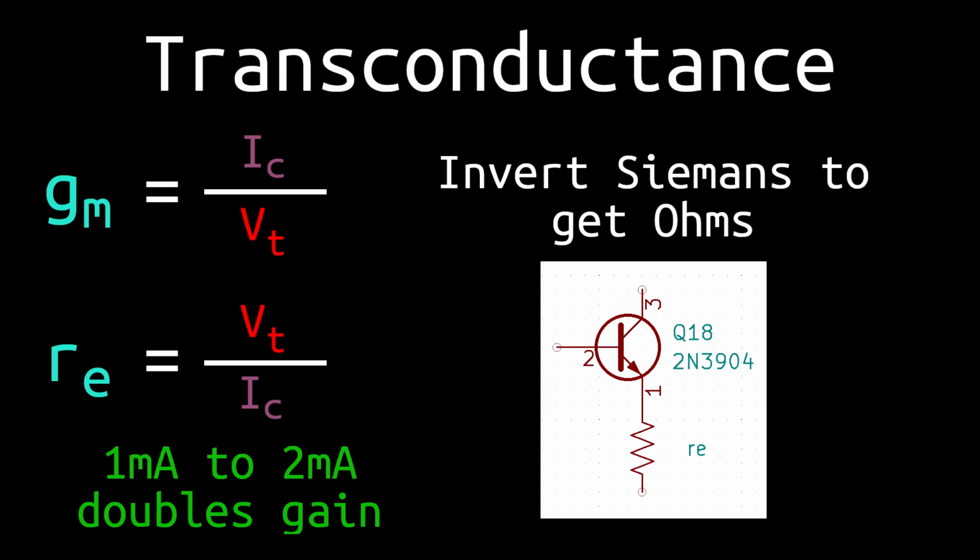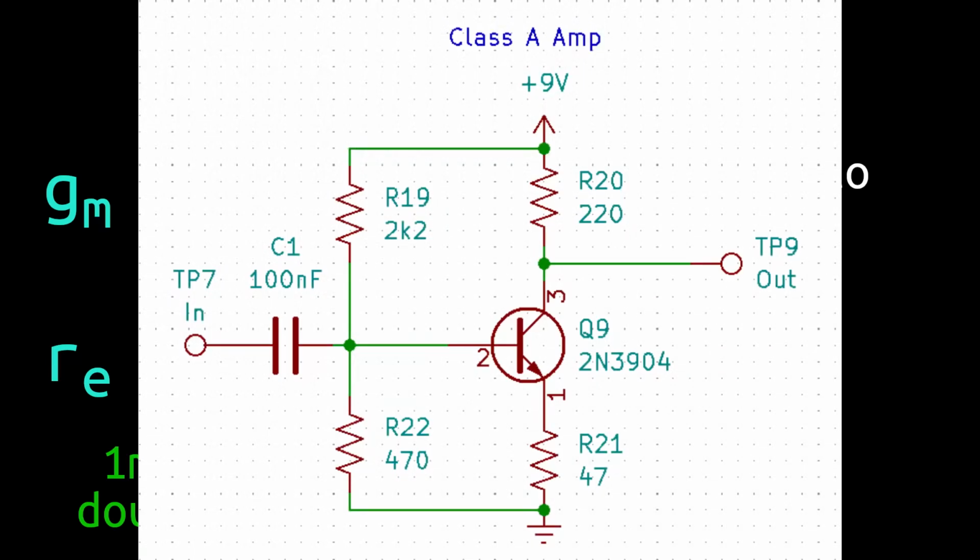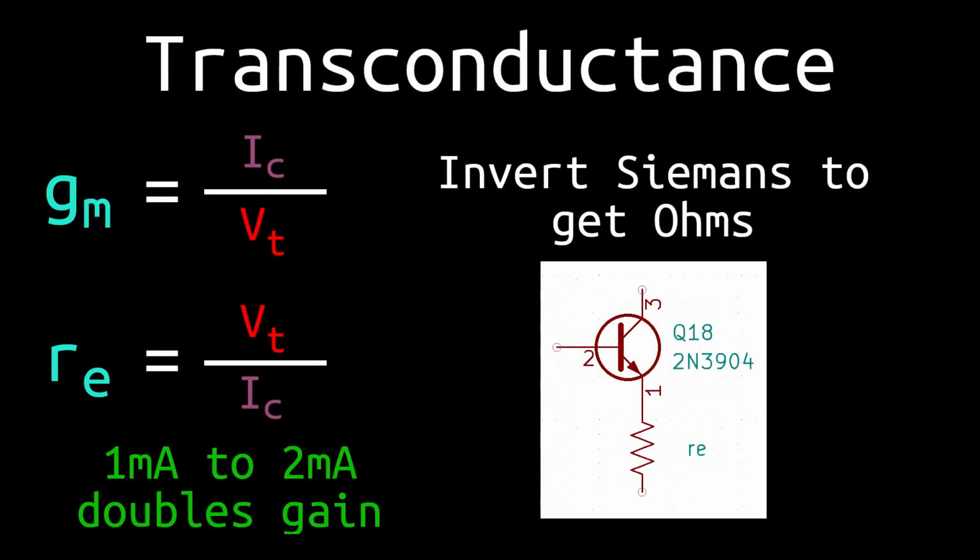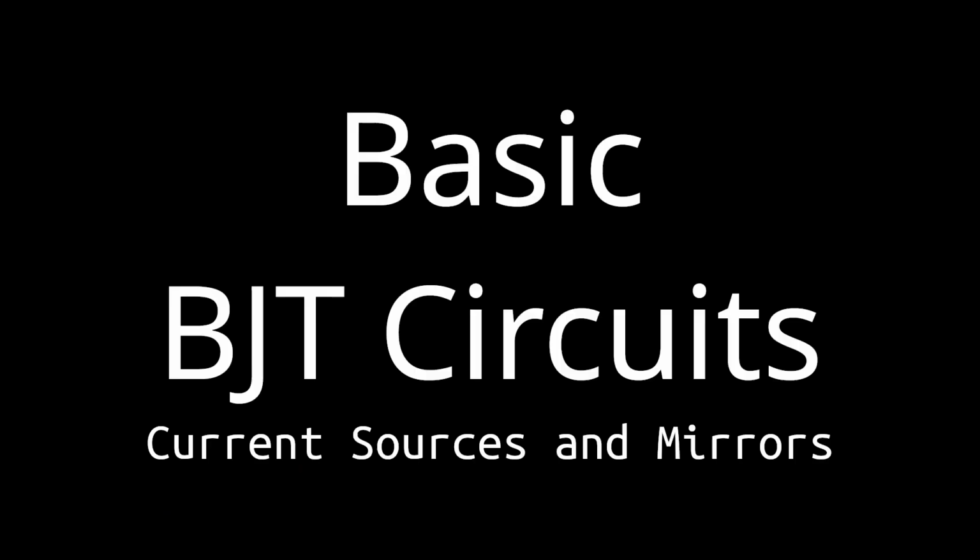Even a small change in the collector current from 1 milliamp to 2 milliamps will double the gain of our amplifier. To fix this, an emitter resistor of our own is not current dependent, and it will keep our gain and current stable through the transistor. So, the main takeaways from this section should be that first, you can determine the collector current by using the base voltage if you wish, and second, there is always a small emitter resistance which is unstable. So, from this point forward, you can determine whether your analysis needs these two properties in order for you to properly examine the transistor circuit.